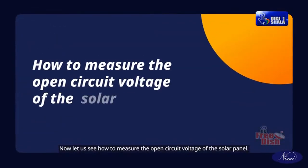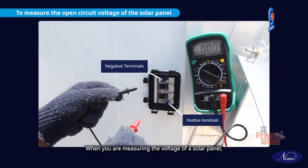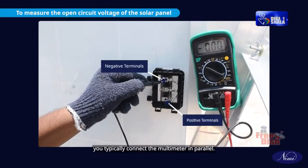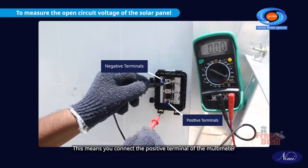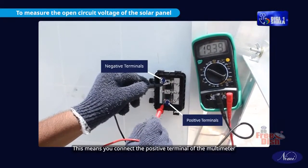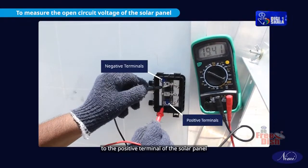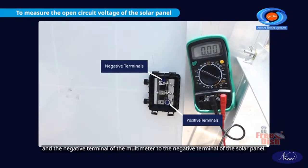Now let us see how to measure the open circuit voltage of the solar panel. When you are measuring the voltage of a solar panel, you typically connect the multimeter in parallel. This means you connect the positive terminal of the multimeter to the positive terminal of the solar panel and the negative terminal of the multimeter to the negative terminal of the solar panel.